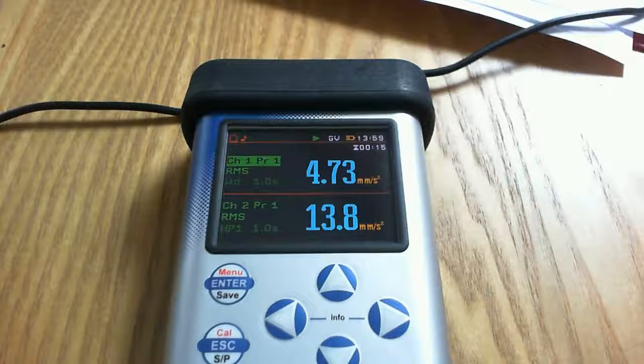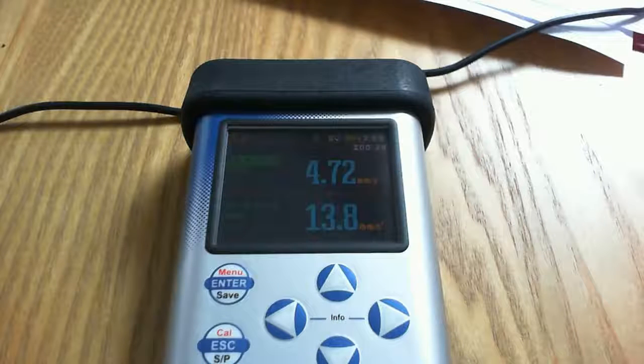If you have the FFT option installed on the analyzer as well, you can also calculate dominant frequency, and when you download the data to the Svan PC++ software, you'll see the type of representation you're familiar with, where it will plot the dominant frequency and the peak particle velocity according to BS 7385 Part 2. Hopefully that was useful.